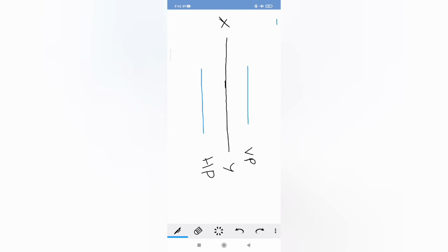In front view, as this is the fake view, let us represent these points as, keep this A dash as constant, and the position of the point B changes. That's why I am representing with the suffix 1, B1 dash, like this. This is A, this is B1. As this is fake view, we have to draw with thin lines.